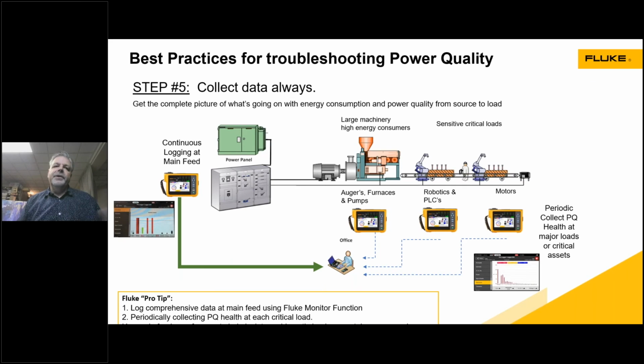In fact, collecting periodic power quality health at each critical load and documenting that over time can help you really narrow down what the problem is when a problem arises. Okay, you might actually be able to trend and find a problem sooner rather than later.